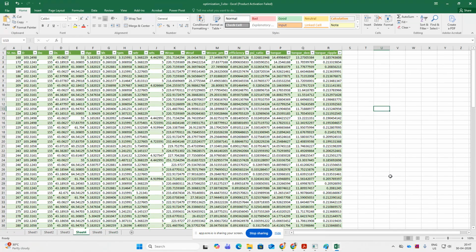You can assign weightage, or prepare your own cost function, with a weightage for every quantity, that is efficiency, core loss, torque ripple, torque density. You can prepare a normalized expression and get the optimized design on your own.